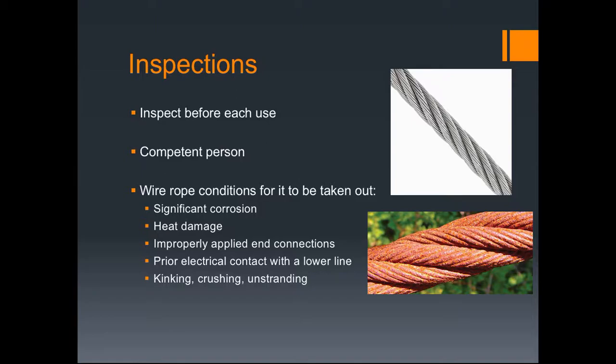So this competent person is really essential in inspections, and you must always have one when inspecting a crane. And the most important thing when inspecting a crane is you must look for what kind of ground it's on, the type of weather for the day, and if any of that is sketchy, you should just delay the crane use for a different time.